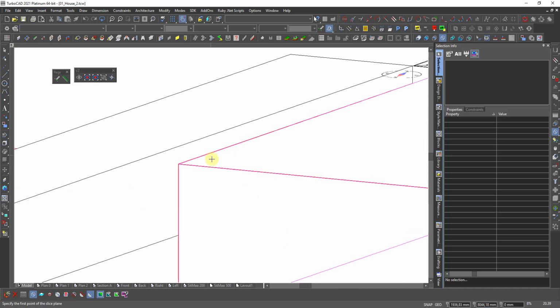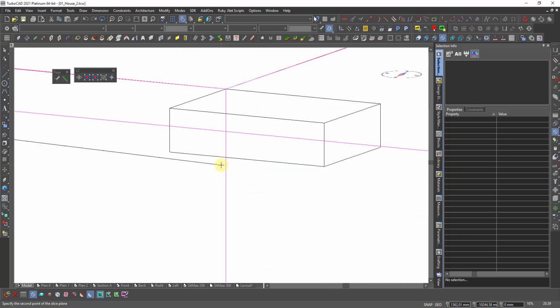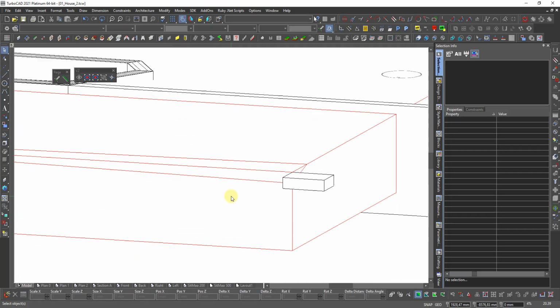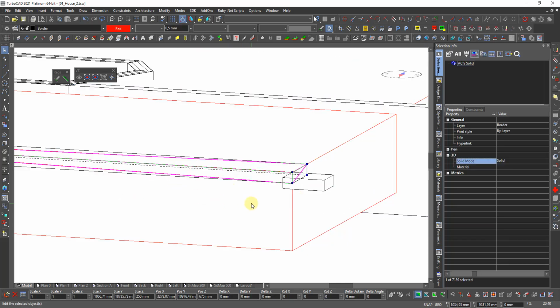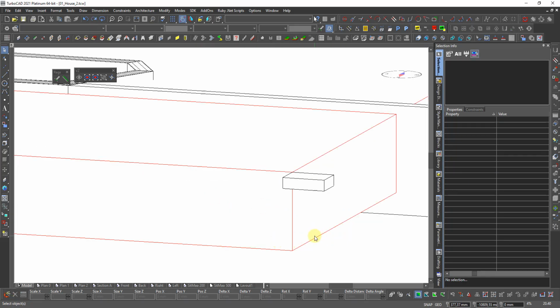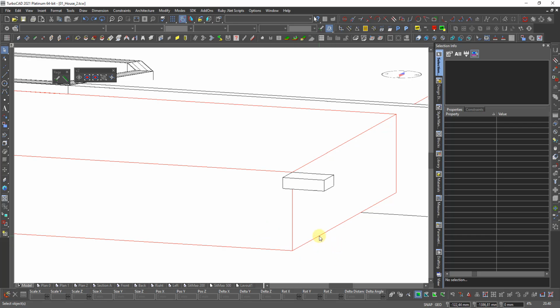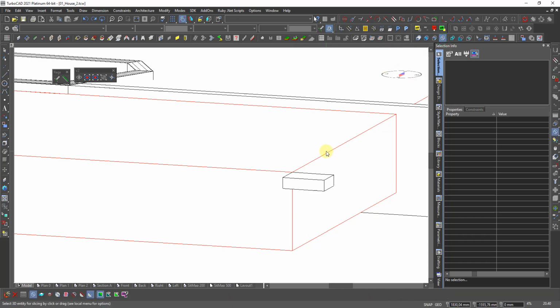I want to slice from this V and down to, there's a V under here, to this V. And then I want to take this Y, no. Control Z. I have workplane by facet. I select. I want to slice it, and I say I want to slice this one.